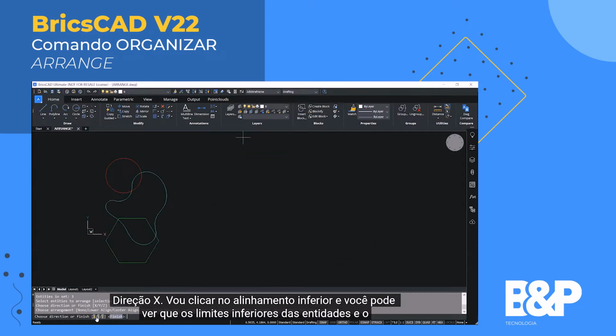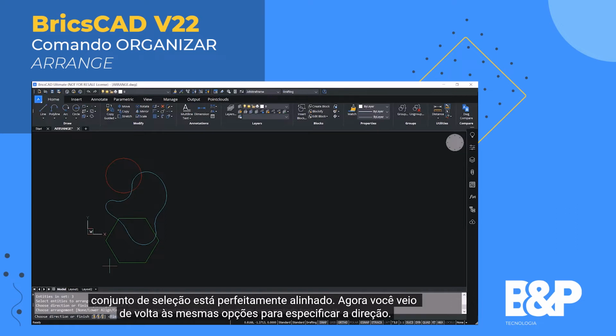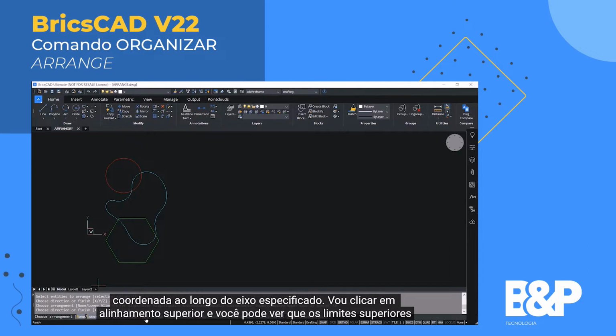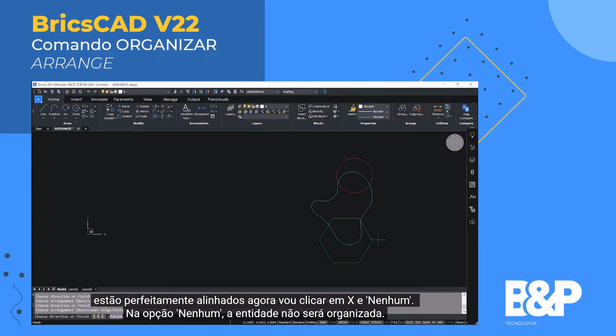I'll click on lower align, and you can see that the lower bounds of the entities and the selection set are perfectly aligned. Now you come back to the same options to specify the direction. Now I'll click on X again, then I'll click on upper align. In upper align, the upper bounds of the entities and the selection set will get aligned. The upper bound is defined by the highest coordinate along the specified axis. I'll click on upper align, and you can see that the upper bounds are perfectly aligned.